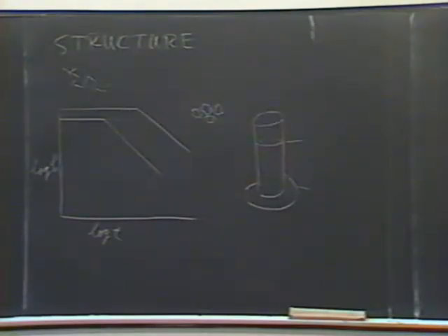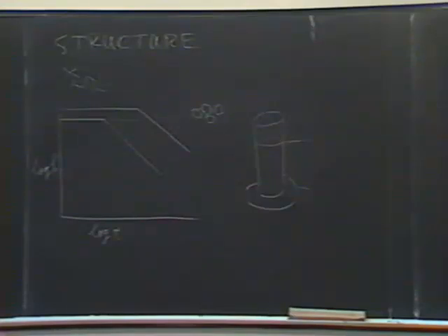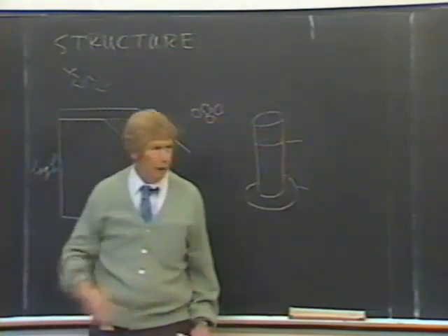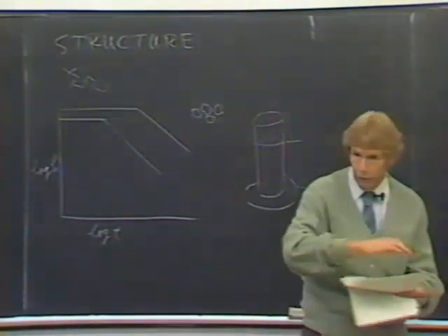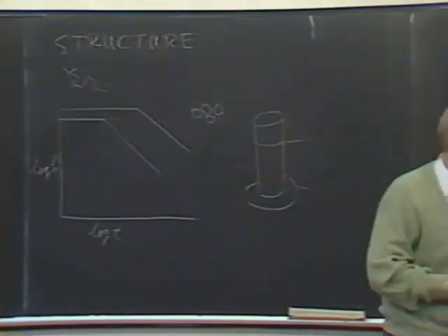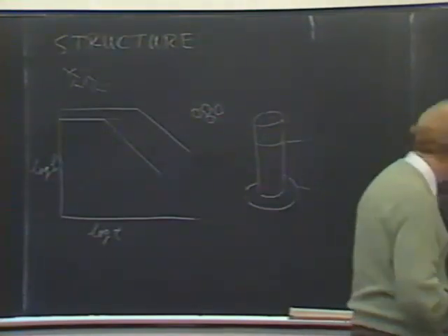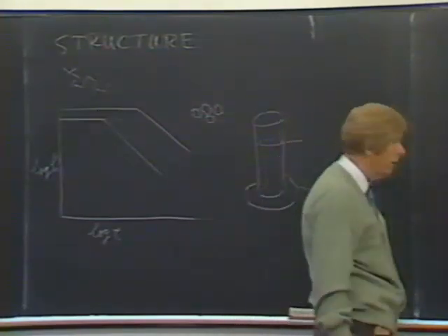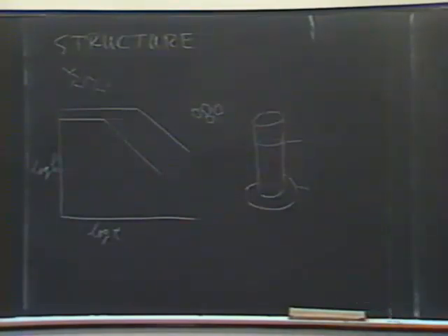Well, so far what I've described is sedimentation in cylinders, just static sedimentation. You stir it up and let it settle. It's useful because it gives you some information on how the material behaves without velocity gradients and without shear stress on the bottom. But in order to study the deposition in real systems where the water is flowing, it's necessary to observe deposition from flowing water.